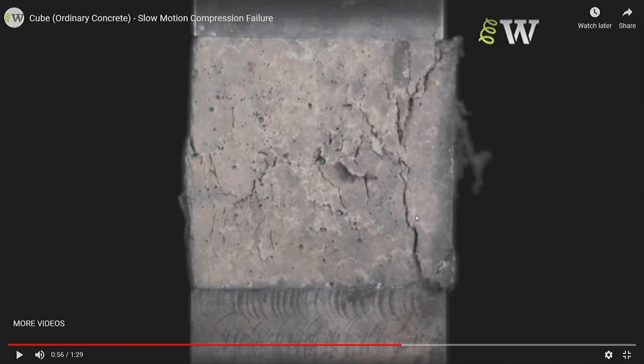And this is very important, and that's how many of the materials which are weak in tension, like concrete, fail. So if you somehow stop that from happening, so if you make them not expand sideways, then they will take a higher amount of compressive force. So because concrete is weak in tension, if you apply a compressive load in this way, it will try to expand in the lateral direction, or have tension in the lateral direction.